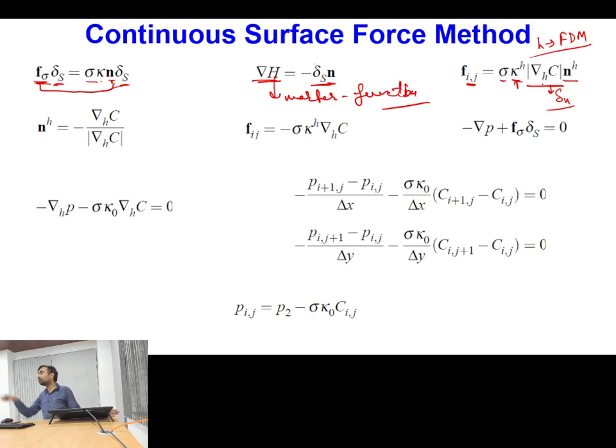It means there is no gradient of surface tension. Okay, I am using a pure system. At the same point of time, I am making a second assumption that there is no temperature gradient present across the interface, because we know that if there is a temperature gradient, then surface tension is also a function of temperature. If for some fluids the temperature range in which we are operating is so small that the change in surface tension value is very small in that zone, then also I can use this particular equation. Is this one clear? So that's why this component will be acting in the normal direction.